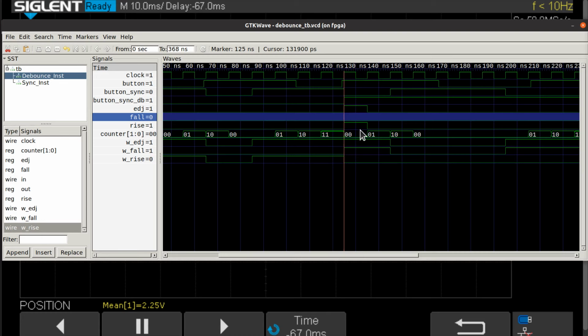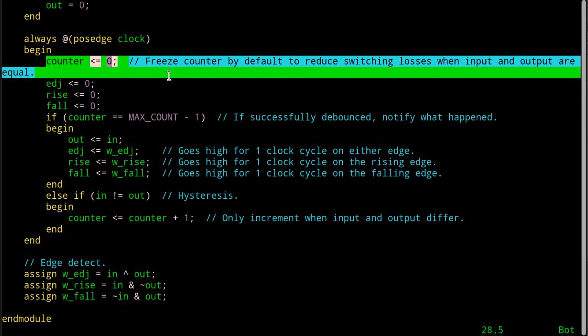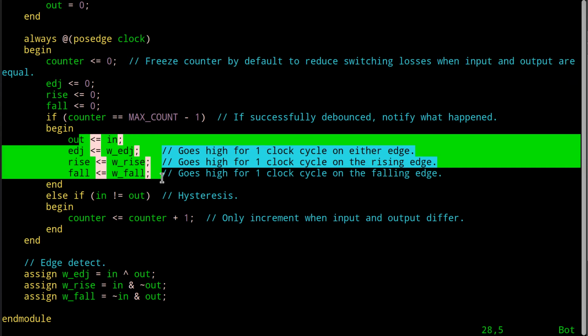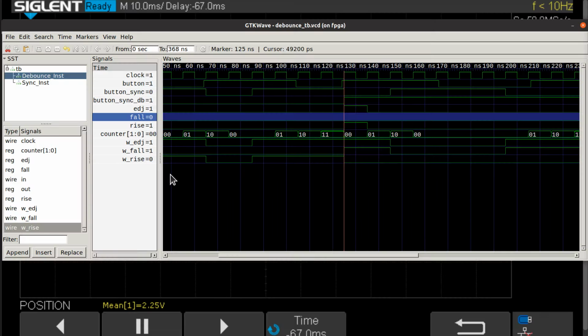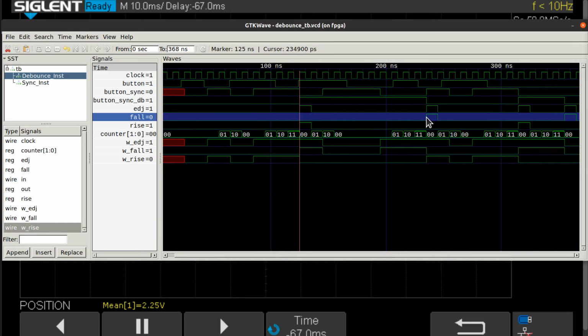And because we've done all that, we're not going to advance the counter here, since we don't assign it a count value, therefore the default kicks in. And the counter will go to 0 along with all these things changing or being assigned for that one period of time. So that's what's going on here. And the same thing will work in the opposite direction, from 0 to a 1 or a 1 to a 0, that's what you see over here.